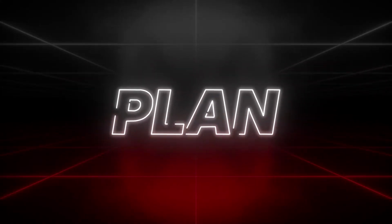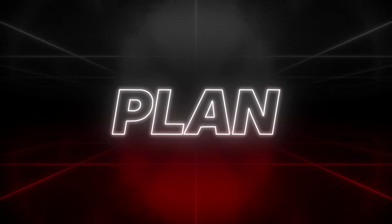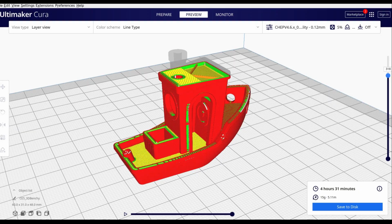At this point, the slicer has a complete geometric plan, but geometry alone doesn't move a printer. Now the slicer becomes a motion planner. Every line you see in the preview is a toolpath, a sequence of movements, each with a speed, acceleration, and extrusion rate. The slicer converts geometry into commands, usually G-code, that tell the printer exactly how to move.